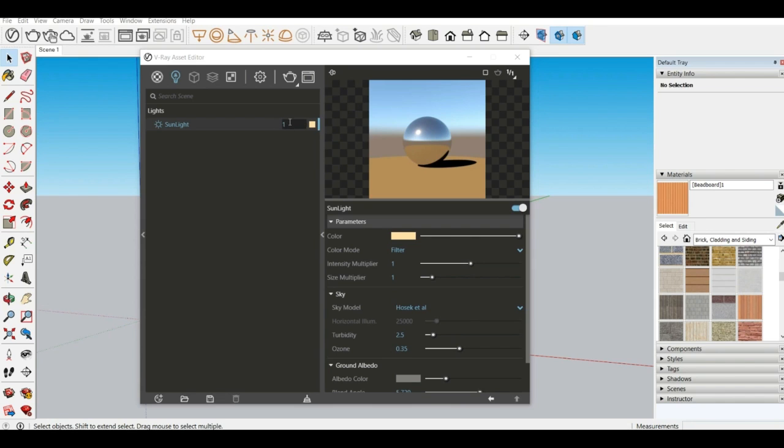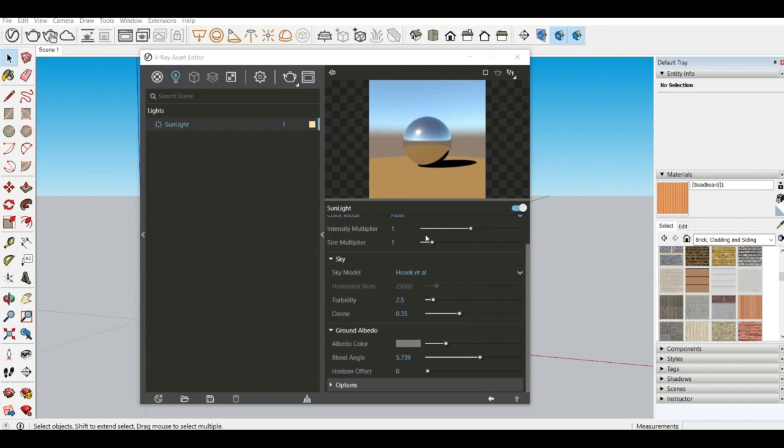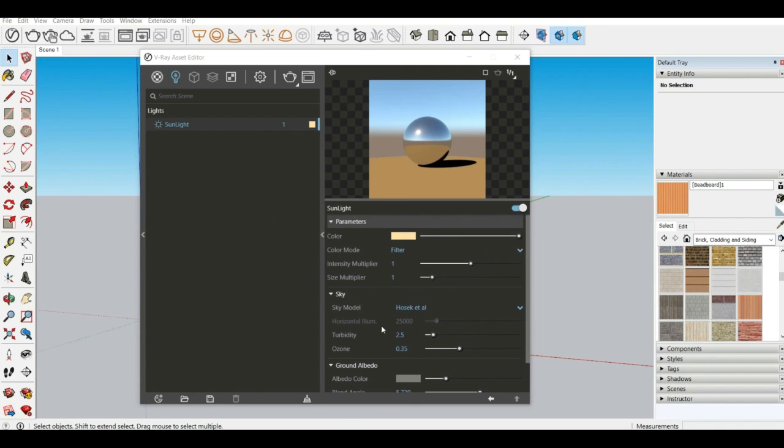So you can do all this by going to the color picker, and besides the color picker is a box through which you can change the intensity of the light as well. But by default the intensity is usually the best, but of course it depends upon you what kind of intensity you want. You can also flip the switch here to quickly switch off the light and show a night view in the model.